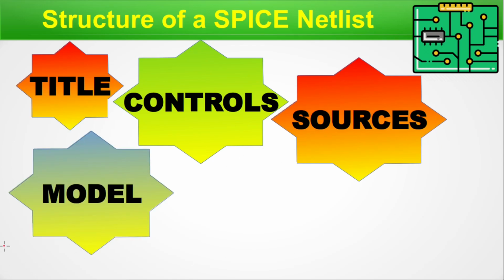Next, there will be models, SPICE models that come from BSIM compact modeling, and all those models are supplied by the foundry. So you don't have to code, you just have to include the available models. For the practice of a student, some models are built into the simulator so that you can pick up those models and directly use them. Additional models have to be included separately, which are provided by the foundry. So those models will be captured in the model section. Without the model, you cannot run any SPICE simulations.